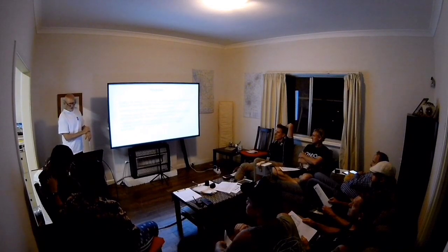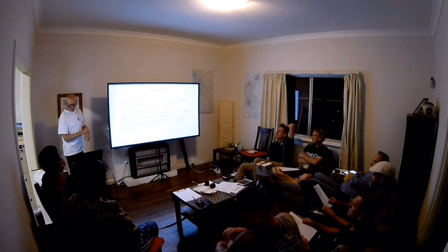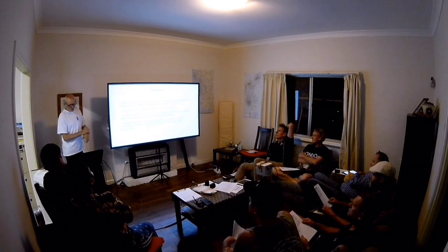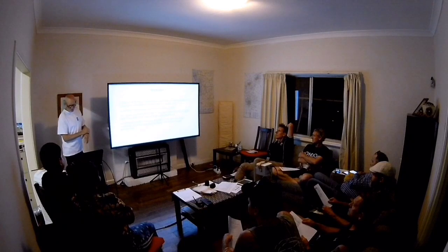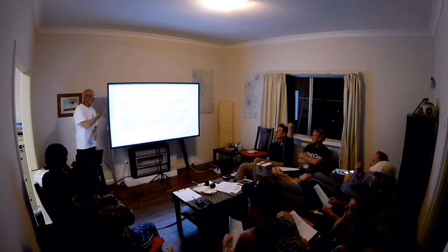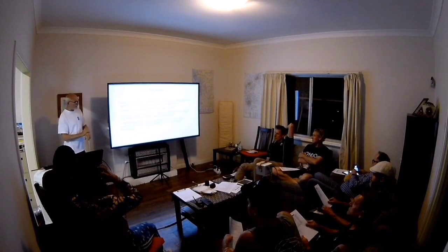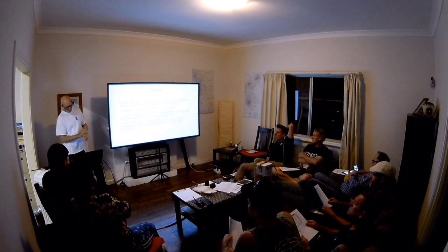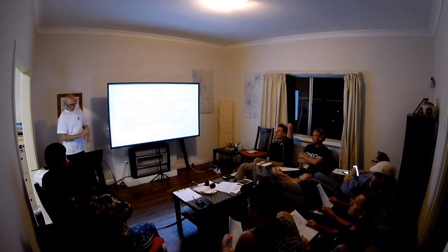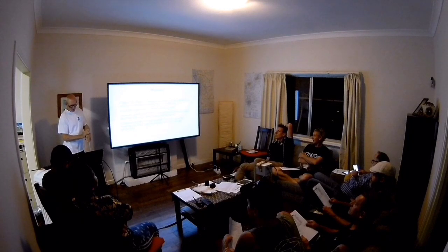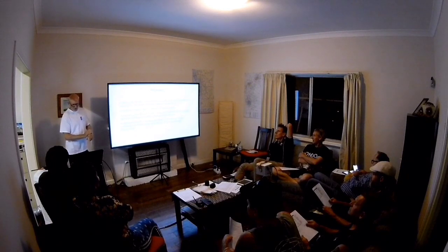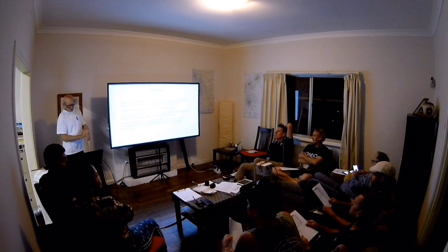A radio or FM receiver is an electronic device that receives radio waves and converts the information carried by them into a usable form, in other words, our voice. An antenna is used to catch the desired frequency waves. The receiver uses electronic filters to separate the desired radio frequency signal from all other signals picked up by the antenna. An electronic amplifier increases the power of the signal for further processing and finally recovers the desired information through demodulation.